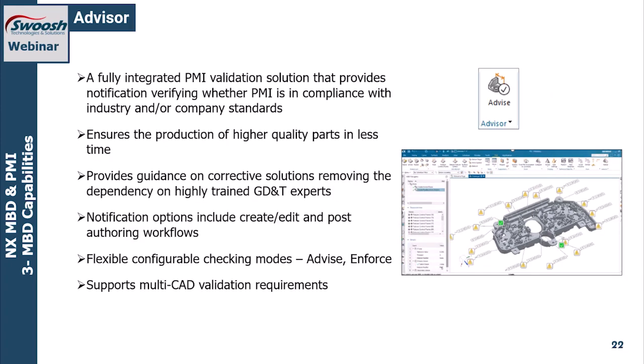Next thing we'll look at here is what's called the advisor. The advisor is a tool you can use inside the software that's going to check the embedded PMI that you've placed on your design, how you've placed the PMI in relation to the features, and it's going to use those different standards. If you're using one of the two standards we talked about earlier in the session, and you apply PMI to your parts, the software is checking in the background with the advisor and is going to look at the PMI applied to the features on the part.